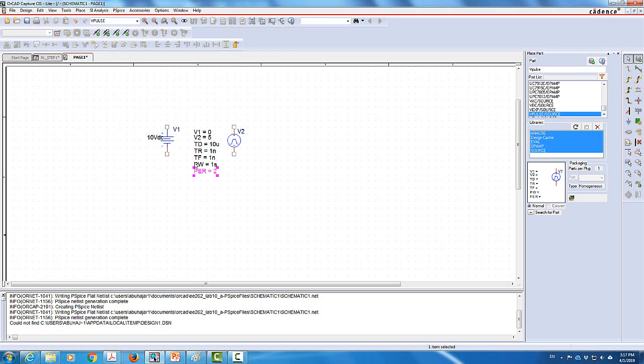This is another trick here when you want to simulate a complete switch. Now remember that when you build this in the lab, you're going to have a rectangular pulse. So you're going to see a rectangular pulse, so you wouldn't use this slow pulse. It's not very effective. You're probably going to use a pulse width of 20 microseconds or a period of 40 microseconds when you build a circuit in the lab. However, for simulation we can do that here, and that's really good.